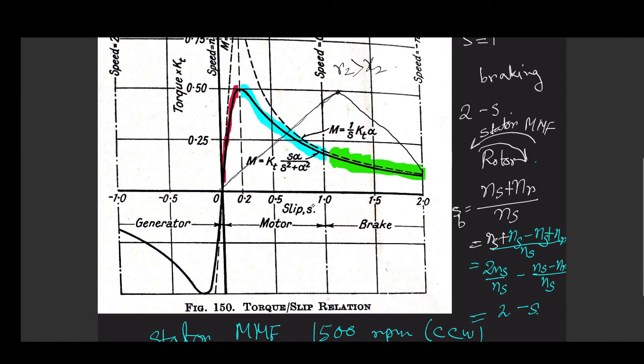If in any interview your interviewer asks what the critical value of R2 is, because rotor resistance is proportional to starting torque: the critical value of R2 is X2, beyond which the maximum torque point is not realizable in the motoring region.